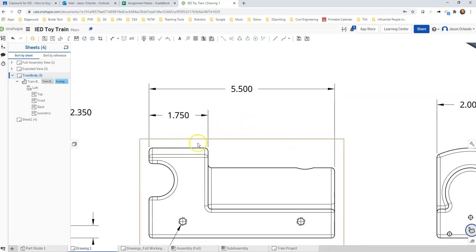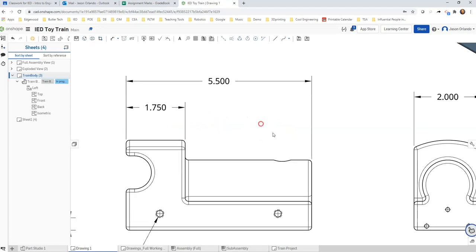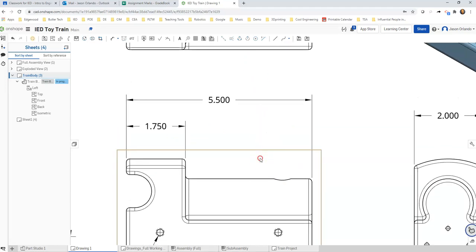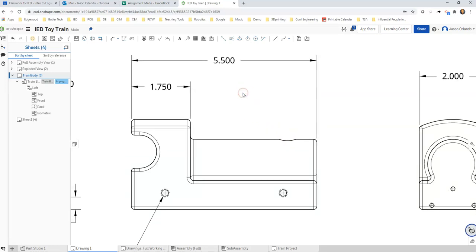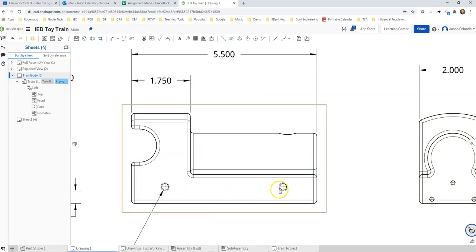So for this feature, where's the divide between this section and this cylindrical section, that provides me really both lengths. I do have this whole feature that I need to understand where it is, but I'm going to do that in a different view, from the top view, where you want to dimension holes generally, in the view where you can see them as a circle. These holes down below, I need to understand horizontally where they occur. So let's dimension those.